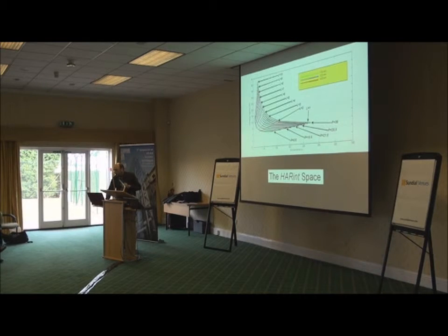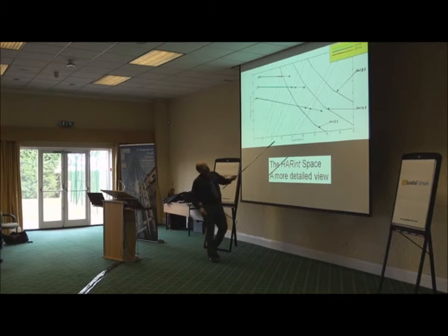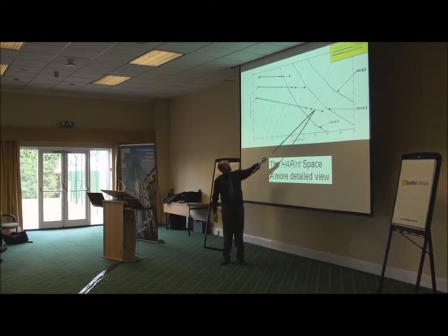And what we can start imposing on them, we can start putting average traveling time and average waiting time on the same curve. So if we zoom in, you can see that's 4 lifts at the smallest speed, 4 lifts at the next speed, 4 lifts at the next speed. Then to move further, it's ridiculous increasing speed above that value. You're not going to get that much benefit. So what do you have to do? Increase the number of lifts.